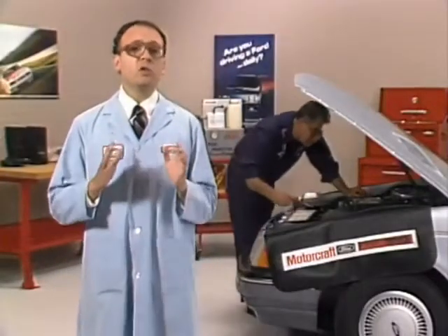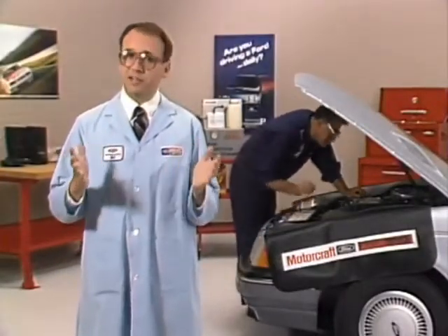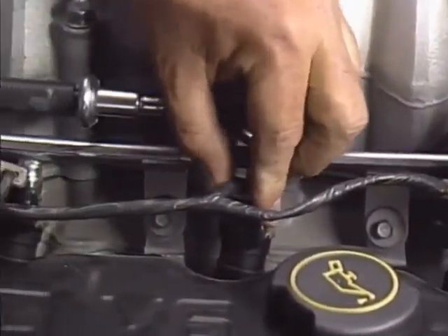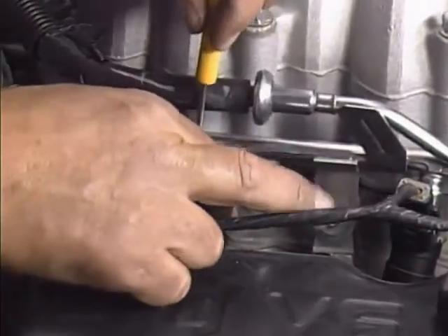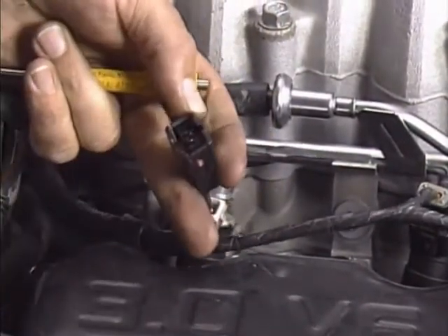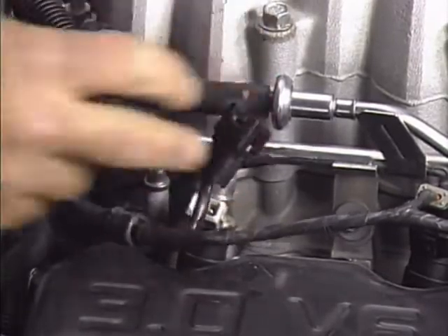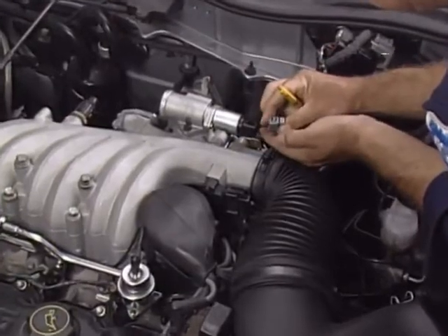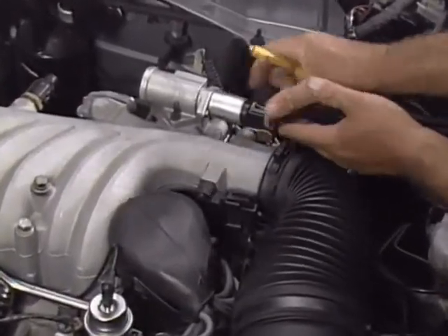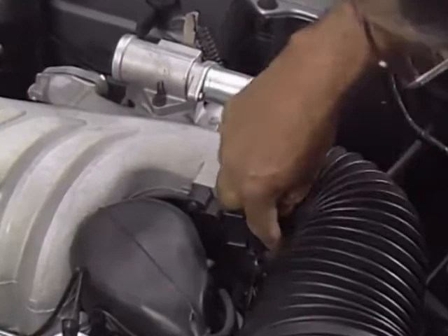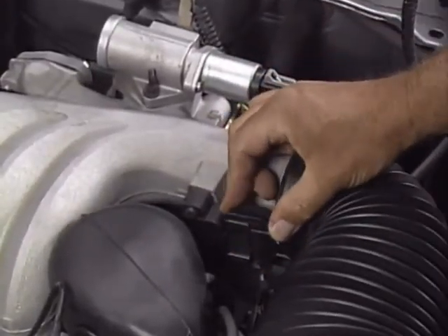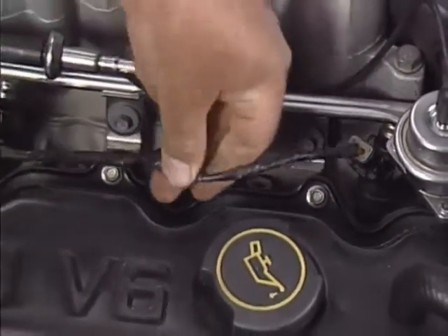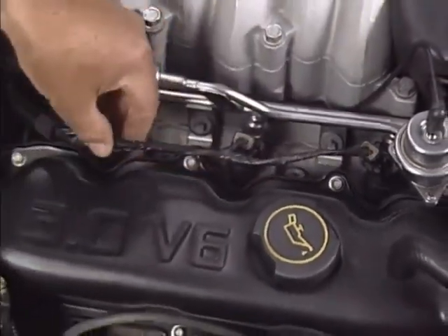Of course, the fuel injection system is also an electrical system, so you'll want to check the connectors and the wiring harness. Check all of the fuel injector connectors to see that they're securely attached and that the connectors themselves aren't damaged or corroded. Do the same for the connectors at the throttle air bypass valve and the throttle position sensor. Check these last two components too for secure mountings and signs of damage. Then go on to check the fuel injection wiring harness for signs of damage or breaks in the insulation.